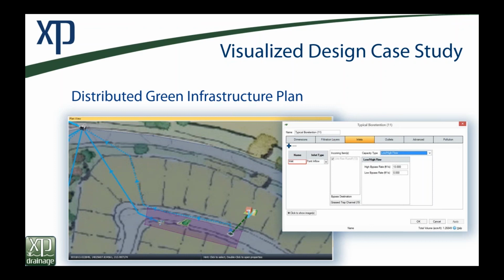Okay, so a lot of these facilities, it's a sandbox. You can't just turn the fire hose on the sandbox and have the 100-year event rush through. You're going to scour your facility away. So you have your minor events move through that facility and have a high flow bypass. That's what we're representing here. You can see in the plan view there's a dotted line showing where that overland flow path would be. The solid line is our pipe.